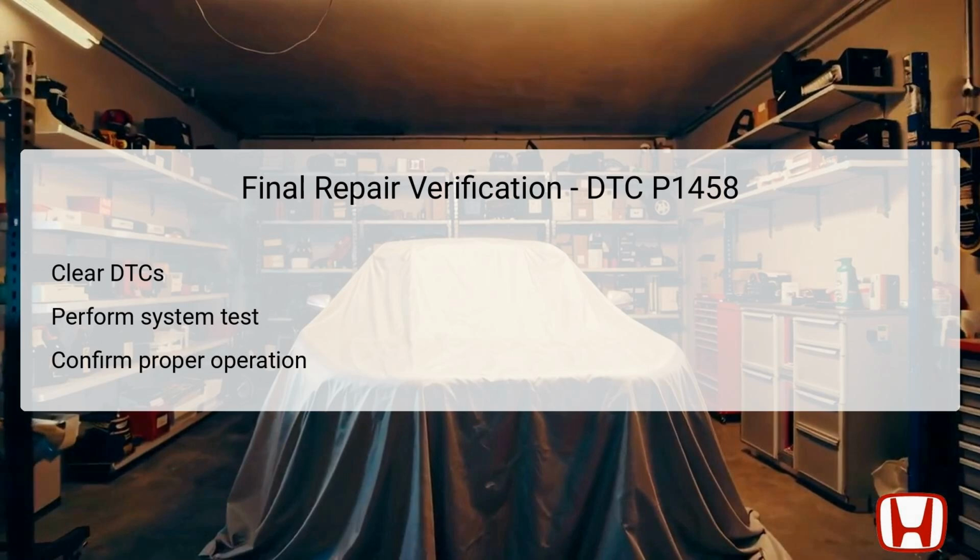It's crucial for the FTP sensor and related components to function properly post-repair to confirm that the initial issue has been effectively resolved. Thoroughly test the performance of the FTP sensor and closely monitor its readings using the Honda Diagnostic System, HDS. If everything checks out and operates normally, this indicates a successful repair of the problem associated with DTC P1458, restoring the vehicle's reliability.